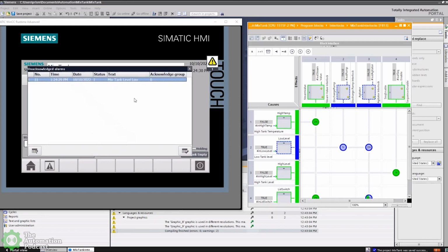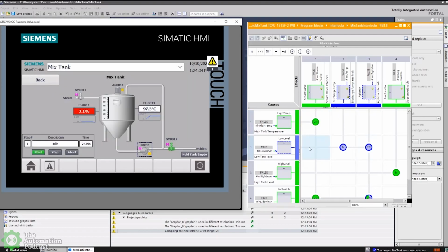there we can see we fired, we got the mixed tank level low alarm. We can see in the cause and effect matrix, we have lost our interlocks for the pump and the agitator, and you can see they are both locked as well. So very easy, like you were mentioning in FAT, okay, we caused a low level, there are the effects across the top, and in a very graphical way, you can see that they are no longer healthy.